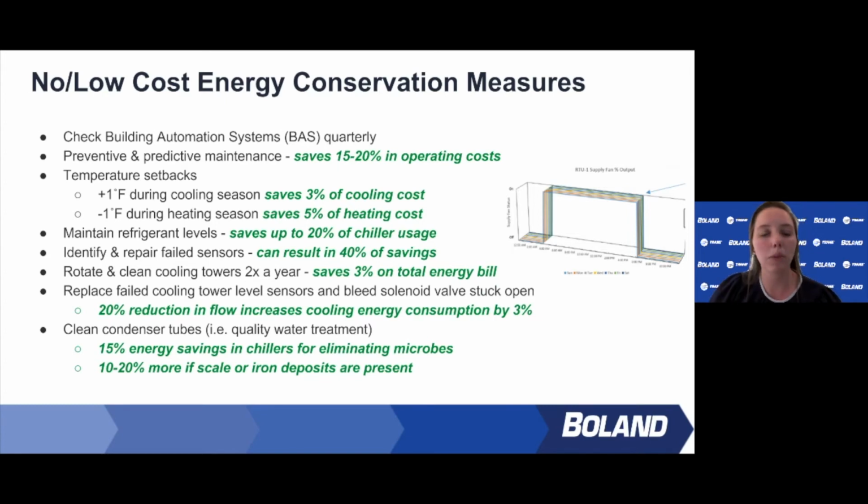We have a water treatment team at Boland, and our specialist said there's 10 to 20% opportunities for energy savings if there's scale on the condenser tube. So we have to go in the system, but if it's there, it's a real energy opportunity for